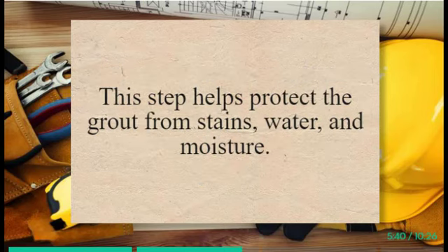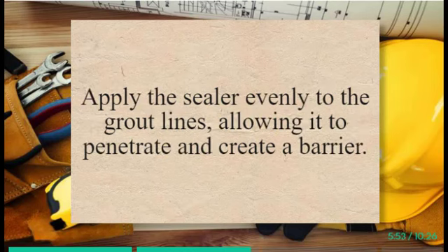Step 10. Apply grout sealer. Once the grout is fully cured, apply a grout sealer according to the manufacturer's instructions. This step helps protect the grout from stains, water, and moisture. Apply the sealer evenly to the grout lines, allowing it to penetrate and create a barrier.